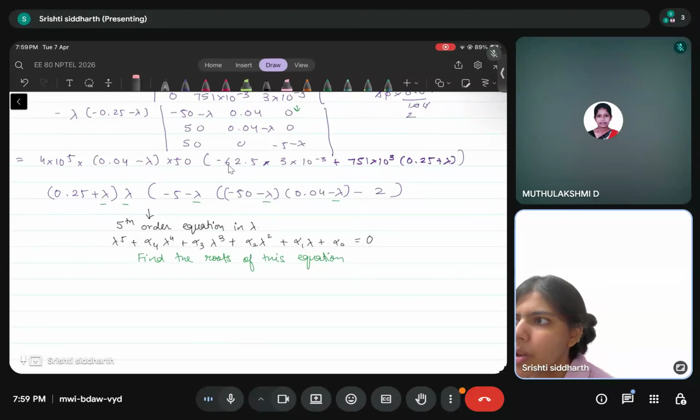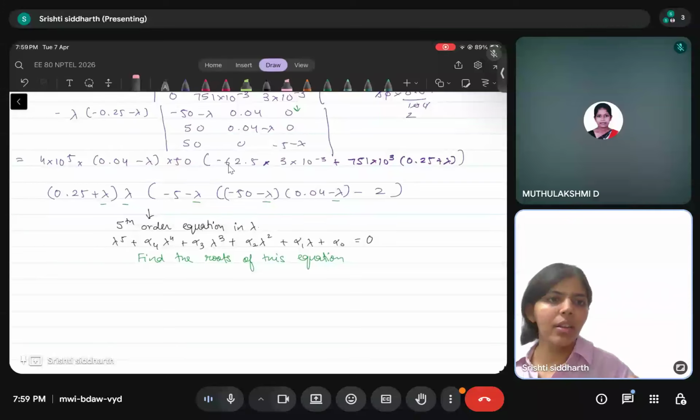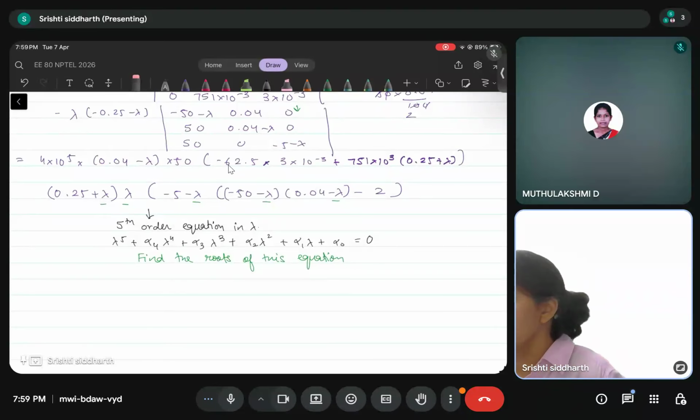And then you have to remember the properties of the state transition matrix to solve a few questions. Then I think it's controllability, observability, and if you do not have a completely controllable observable system, then you have a smaller subsystem, right? Which is controllable and observable. So you can design the controller for that.